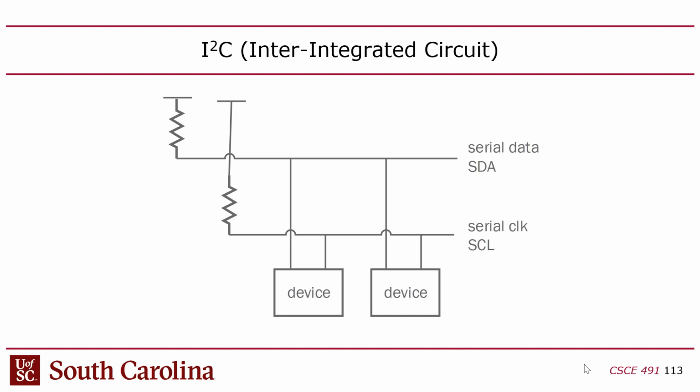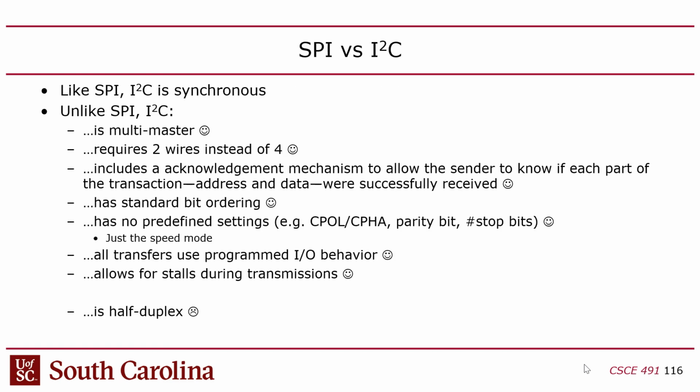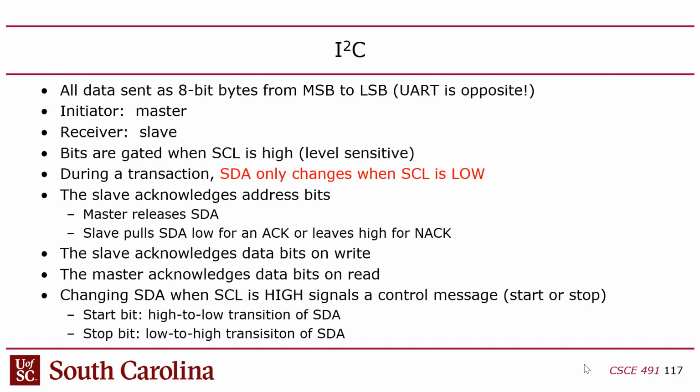And it's also, unlike UART and SPI, a multi-master bus because it's going to take advantage of this open drain technology to allow anyone to be the bus master. So now you don't have assigned roles anymore. Any entity that's connected to these 2 wires can take mastership of the bus, right? Because anyone's allowed to send signals on either wire because of this open drain technique. Right? Okay, so I already mentioned that.